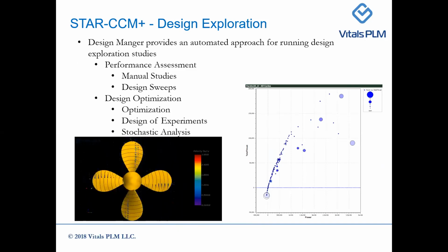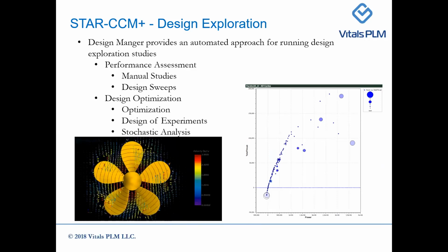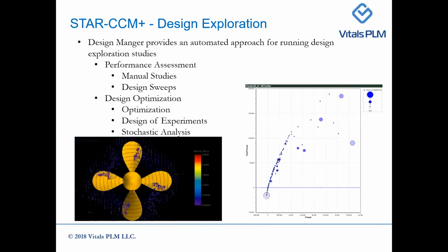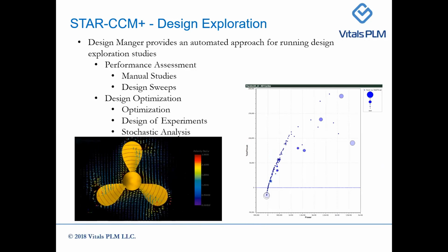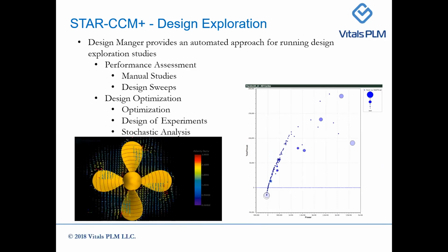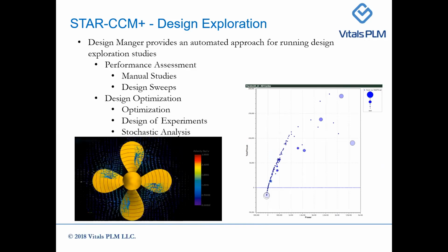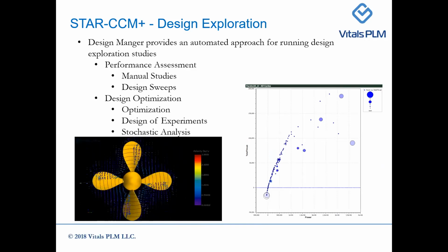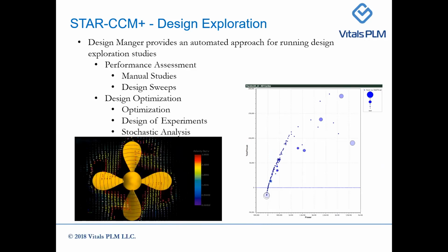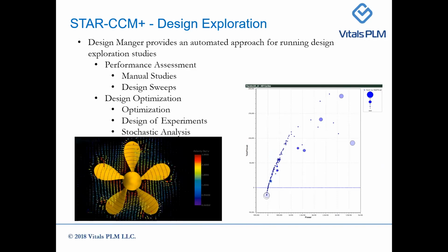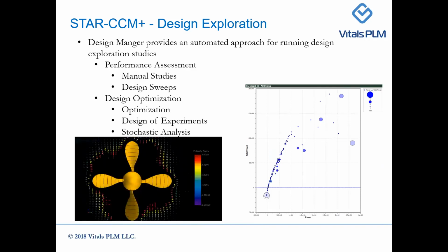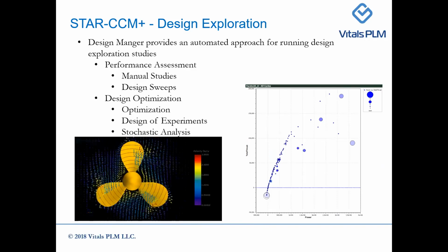In performance assessment you can specify manual studies, like you want to change this diameter or some parameter, and also you can do design sweeps. You can specify a range, and STAR-CCM+ will automatically do multiple analyses at different variables. And for design optimization, it has an optimization cycle, design of experiments, and stochastic analysis.